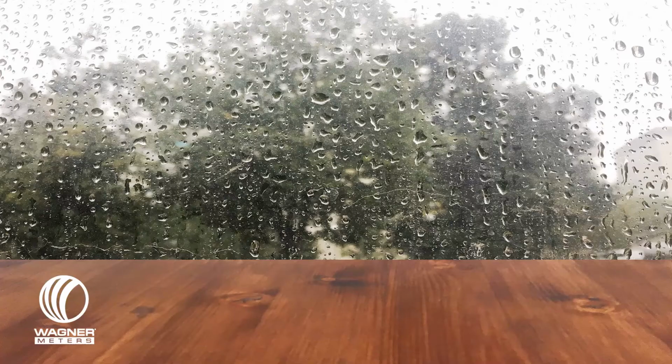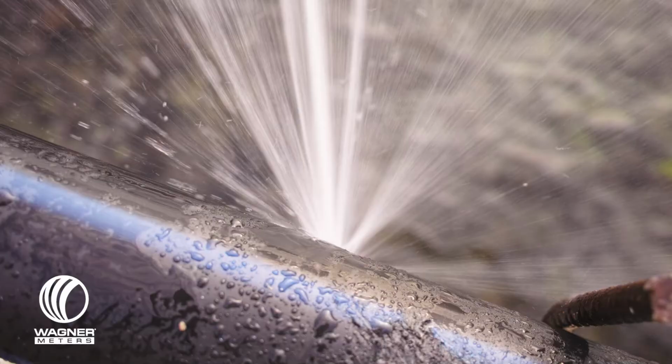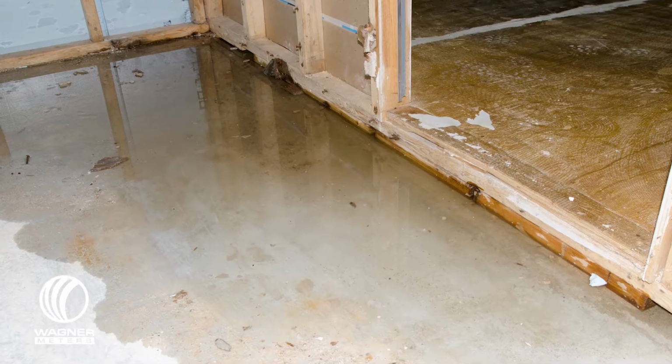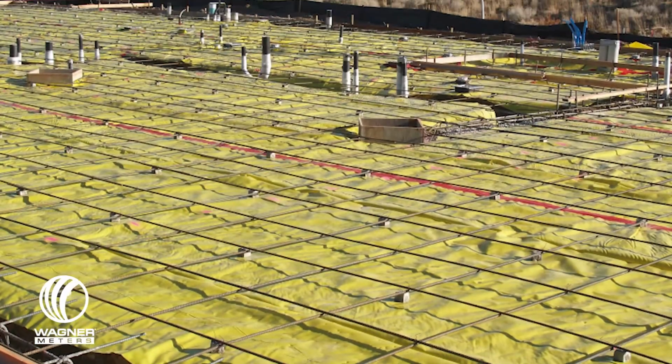So, we see that these problems point to one culprit: the moisture between the flooring and the slab. Where does this excess moisture come from? What causes it? And how can we prevent these types of moisture issues? The source of moisture in the slab could be rain, snow, groundwater, leaks, increased water content, even sprinkler systems. So basically any water not necessary for the concrete to harden. Causes for this can be inadequate drainage, poor subfloor protection during the construction process, or improper vapor retarders. Rushed project schedules can even be detrimental if the slab didn't have time to dry.